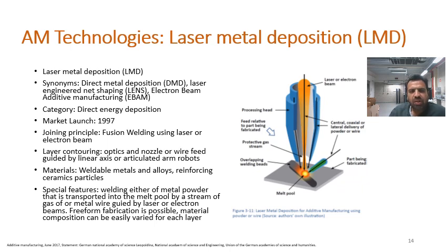Almost all the weldable metals and alloys can be produced by this technology. However, currently this technology is most applied to produce parts of high temperature alloys like Inconel alloys. It's also being investigated to produce Ti-64 parts. This technology is also more suitable for large scale parts.